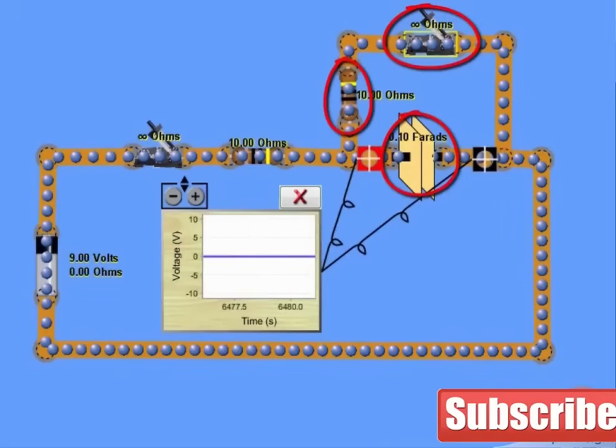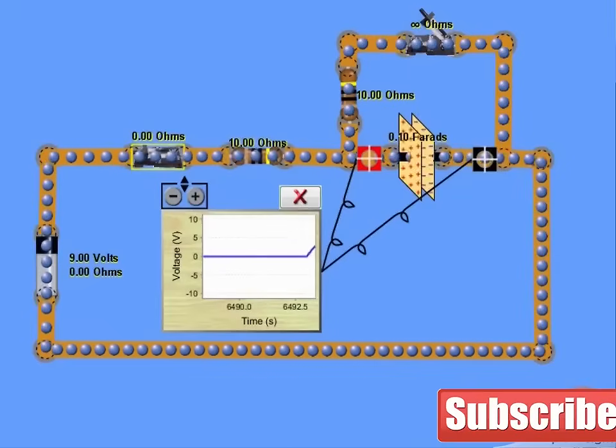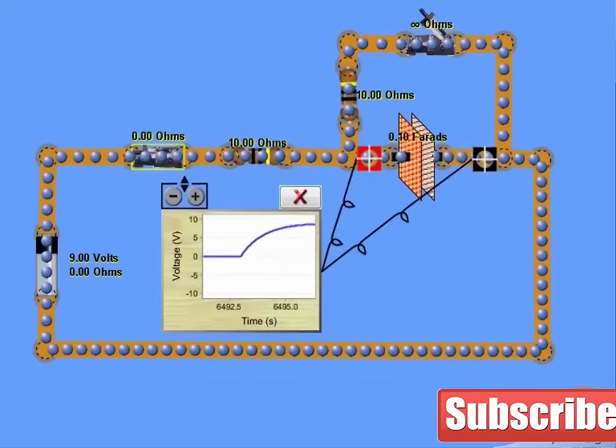If we close the switch on the bottom loop, the charging loop, we'll be able to see on the voltmeter how the capacitor charges. Let's give that a try. We see the voltage rising to the final value, which would be the same as the 9-volt battery. If we remove the battery from the circuit, we see as before, the capacitor holds the charge, remains at 9 volts.